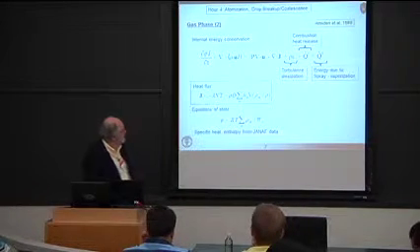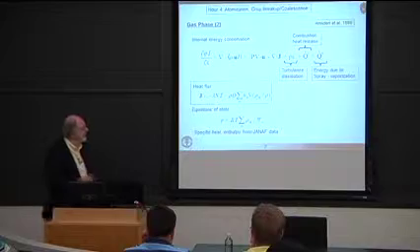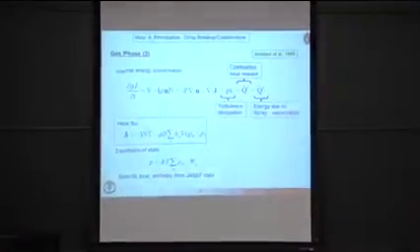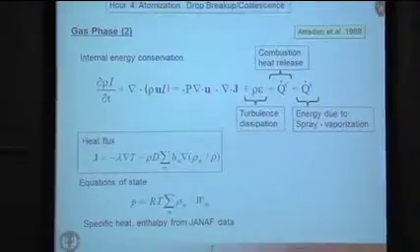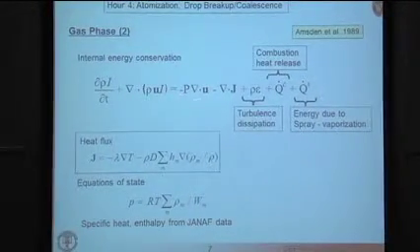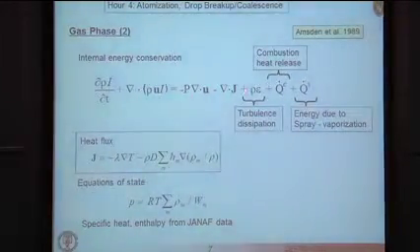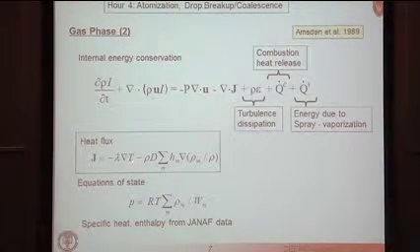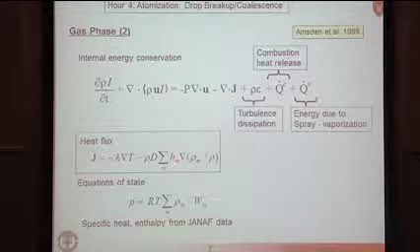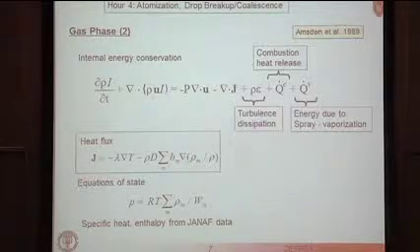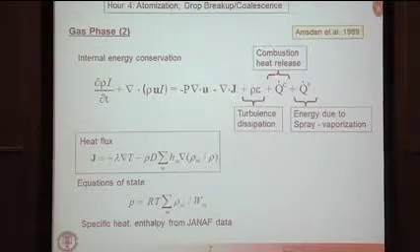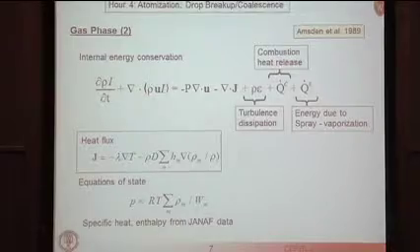Okay. Then looking at energy conservation, here's our energy equation. Again, we saw this last time, written in terms of the specific internal energy, our PdV work term, our flux term involving gradients due to temperature gradients and conductivity, and then species mass fraction gradients carrying with them enthalpies. So that's our heat flux term. We have turbulent dissipation. Combustion, heat release, we spoke about that last time.